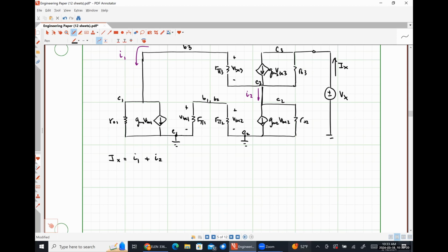Oh, actually, I have made a couple of mistakes here, so let's fix some things. The first mistake that I have made is in my drawing. Maybe this is what you guys were whispering about. Transistor 2 was diode connected, but I didn't diode connect it in my small signal model. Okay, so that should be connected because we have a diode connected transistor, and because my grounds are at the same potential, I could connect these two guys as well.